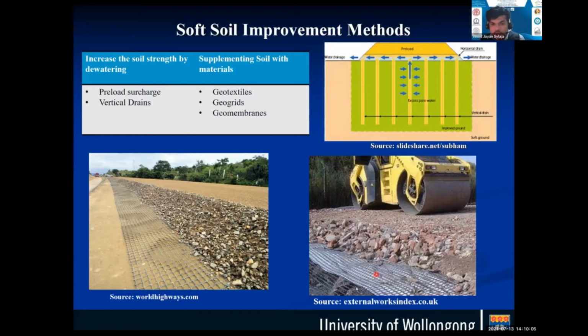So the geotextile here will try to dissipate the excess water pressure developed due to the cyclic loading coming from a truck or a fast-moving vehicle, and the geogrids can provide an additional confinement effect through the interfacial friction developed between the soil and the geogrid. So we are very comfortable in applying this material for various infrastructure development.